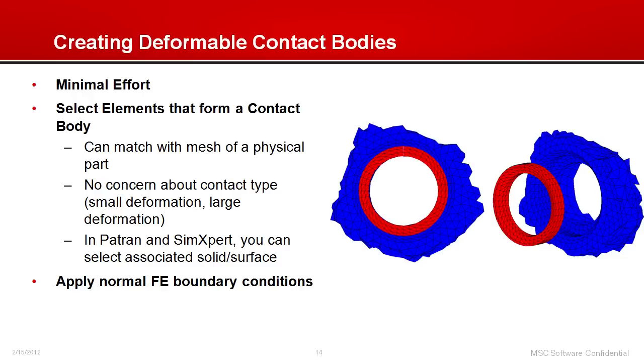So you don't have to be concerned about, hey, if I forgot to pick a few faces on this side here, and then I have a penetration or I have missed a contact and I have to go back and redefine the contact pairs again. So we always recommend to our customers that when you're doing a contact analysis, just select everything and let the program figure out what is going to be in contact and not. Okay.